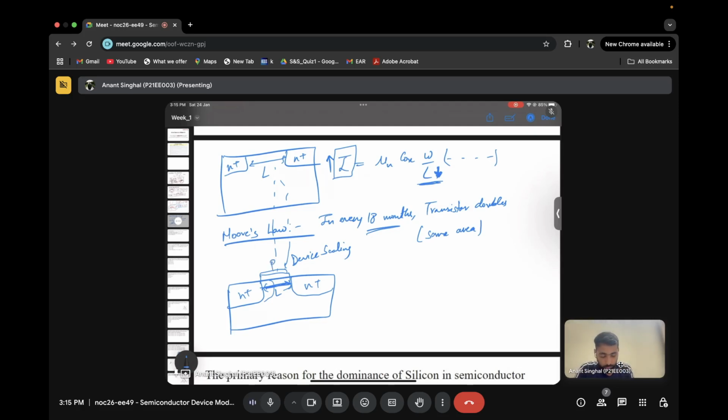So what do we have? We have several leakage currents coming into the picture. These are undesirable, right? We do not want any leakage or anything undesirable to happen to our device. So this is related to what are called short channel effects. We'll be discussing short channel effects in this course in maybe the last section of the course. But I'm just trying to give you an idea of what device scaling is and why we even need it, because we want more and more current.